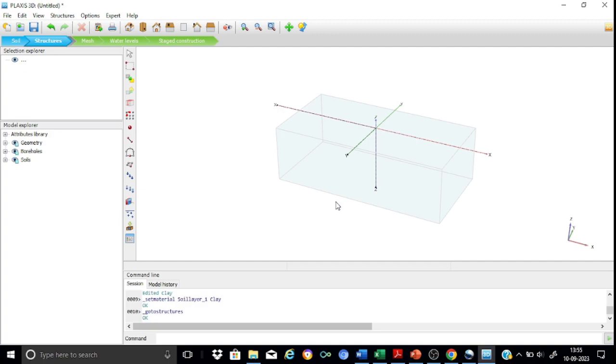As we did in the earlier tutorials, first we create a surface, we extrude it, and then we decompose this volume into surfaces, and then delete the unwanted volumes as well as the surfaces in order to obtain the required surfaces. After modeling the surfaces, we'll convert these surfaces into plates and then assign the required properties to the plates. Okay, so let us proceed.